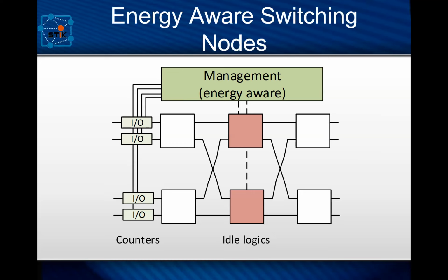In the case of seeking to reduce electrical energy consumption in the data plane, it is possible to disable certain resources, such as switching elements in the switching fabric. For instance, in the middle stage of the closed switching fabric, it is possible to turn off one or more switching elements, depending, of course, on the intensity of traffic offered at the input of the network. When we turn off one or more switching elements in the middle section, we save electrical energy.